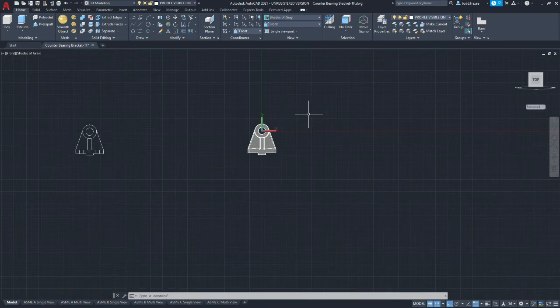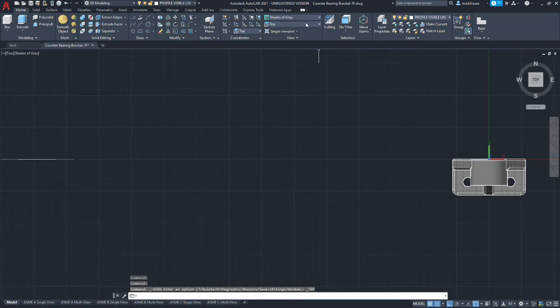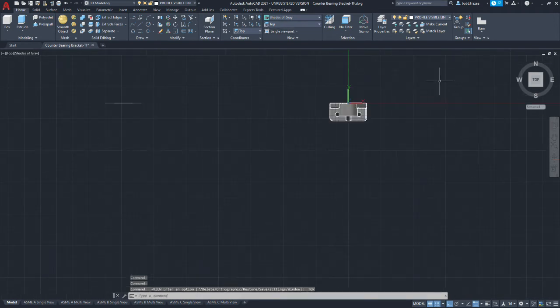We're going to follow these same steps 2 more times to do the top view and right side view. So let's change our UCS to top, which puts us on step number 12 in the written procedure. You're now looking at the top view of our model.